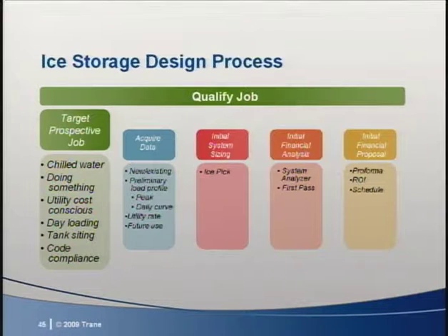Finally, many owners would prefer air-cooled chillers, but local or state codes may limit the allowed system capacity. Some codes, such as California Title 24, have an exception for systems with energy storage. Or the addition of ice will allow the same capacity chillers to serve a much higher peak load.